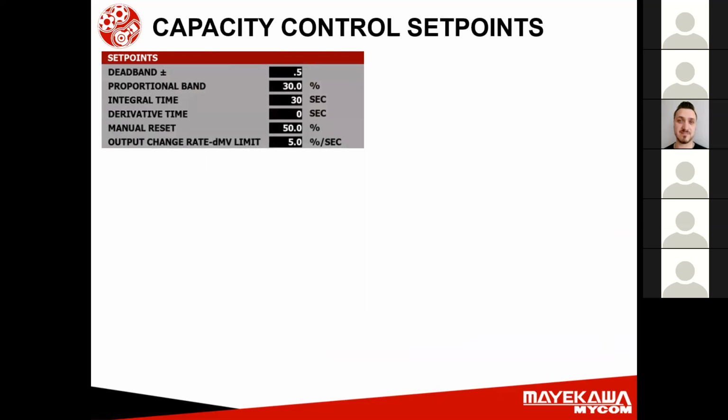PID is an acronym for proportional band, integral, and derivative. This control action allows a measurement or process variable to be controlled at a desired set point by continuously adjusting a control output. These control parameters act on the error or deviation between set point and process variable, in this case, suction pressure. Let's review the parameters of the PID control.